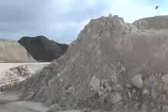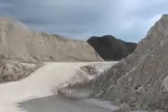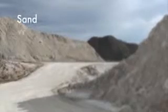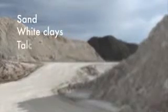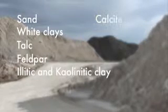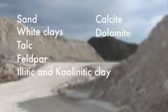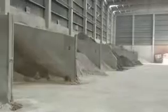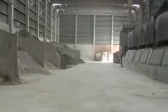Tiles are made from basic components that are readily available from Mother Earth. Raw materials such as sand, white clays, talc, feldspar, oolitic and kaolinitic clays, calcite, and dolomite are quarried and refined. Using heavy construction equipment, the raw materials are brought to the plant where they are stored prior to mixing. They are placed in holding areas, classified by type using a simple numeric reference system.